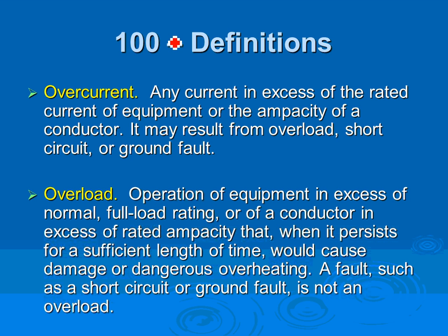So, because it confuses the people, why do the circuit motors need an extra protection? They're important loads and expensive loads. Would the circuit breaker by itself protect the motor? It would, but not fast enough to protect the motor itself. It will protect the conductors, it will protect a lot of stuff, but not fast enough to protect the windings.